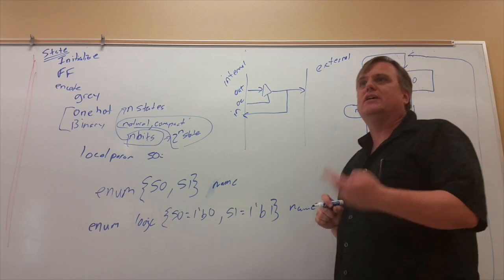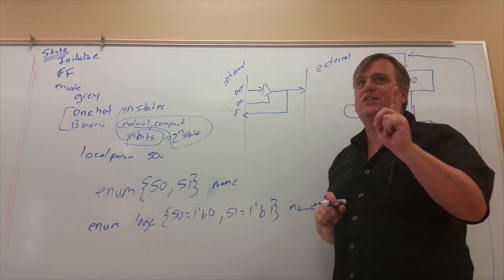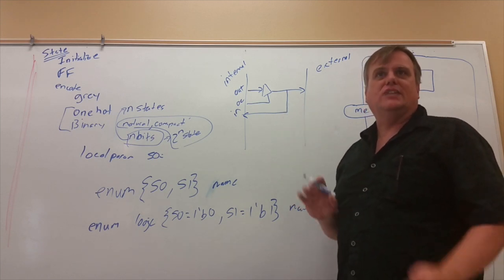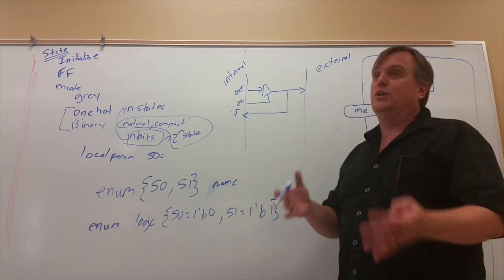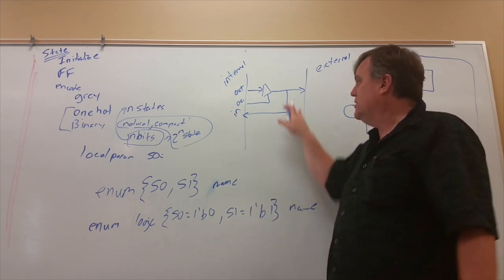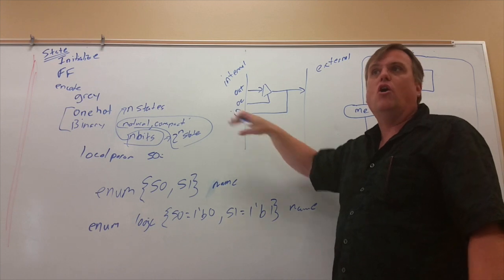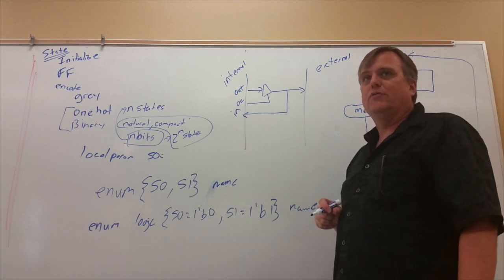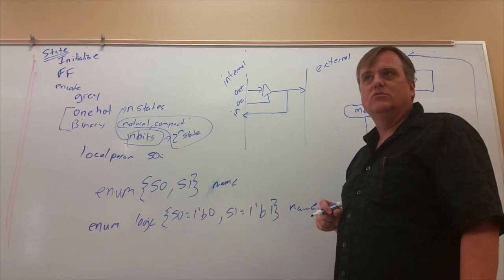So the only spot you can synthesize something else, you can only synthesize a Z, and only on an I/O, by setting the output to not be enabled. But if you still intend it as an output, you technically still get a Z, because you're not using this. There's no draw. Why would I ever want to synthesize Z?